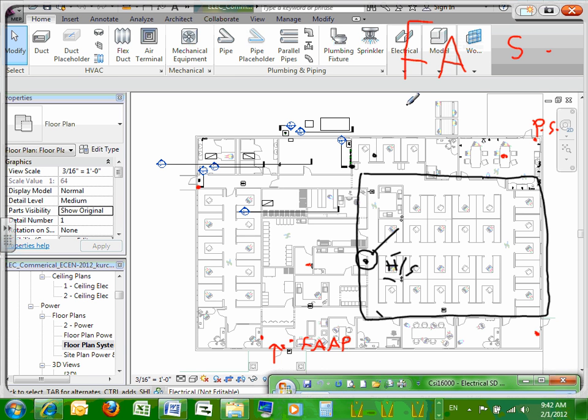You might be in a conference room on a conference call, talking to people, and the fire alarm might go into alarm, and you might not be able to hear that. So what we want is a visual only, a strobe only in the conference rooms, pretty much right as you enter that door.